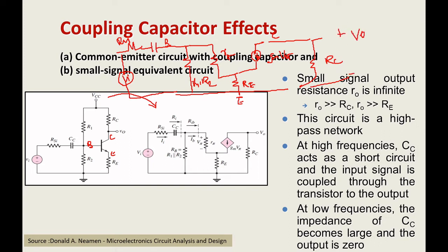I want to calculate what the gain is. Gain is nothing but output versus input. Here in terms of voltage, so I can say V0 by VA. That's it. Here they have taken two considerations, that is RIB. They have taken this as RIB, that is the base resistance. When you look at the base part, what is the resistance it offers, including this feedback part, including this RE part.